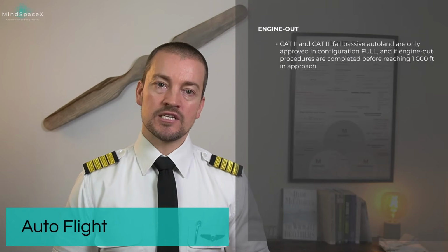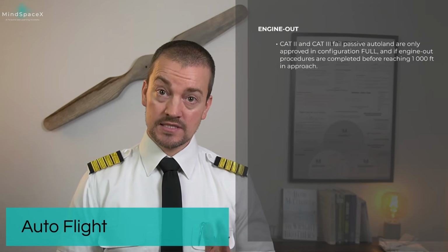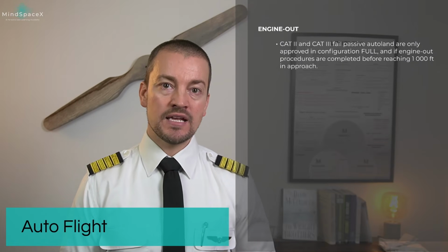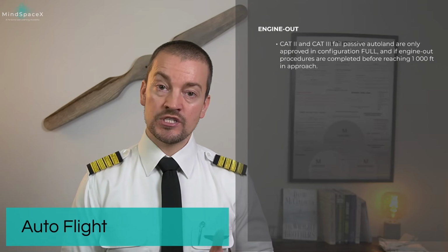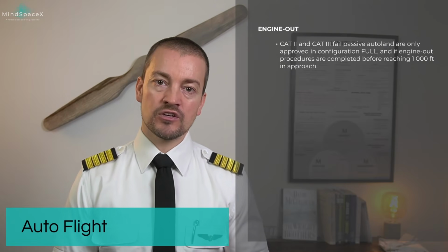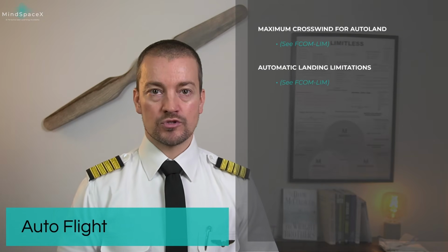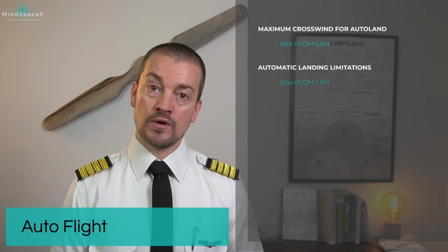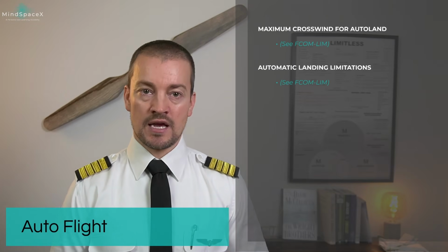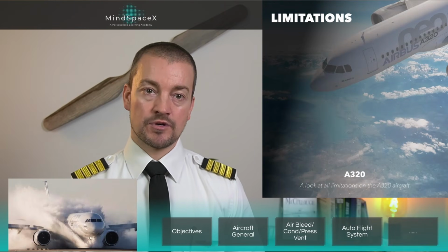Autoflight also has limitations for single engine. Cat 2 and Cat 3 fail passive single autoland are only approved in configuration full, and if engine out procedures are completed before reaching 1,000 feet in approach. So you must have dealt with the engine failure prior to 1,000 feet in order for you to commence and continue the approach. Maximum crosswind for autoland and automatic landing limitations are given in your limitations chapter in the FCOM. And that was it on the autoflight chapter.